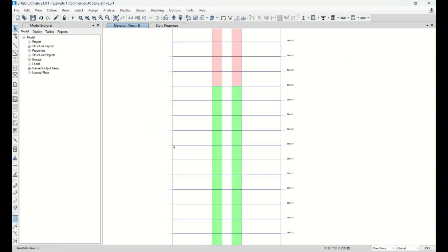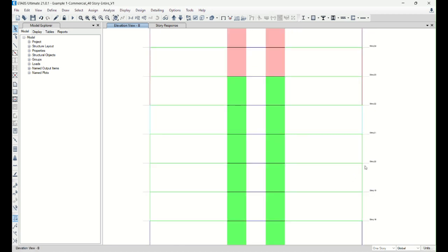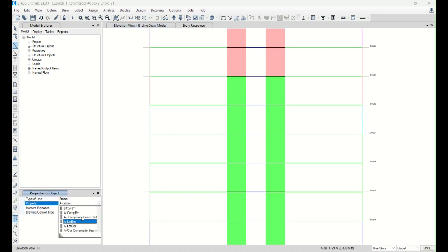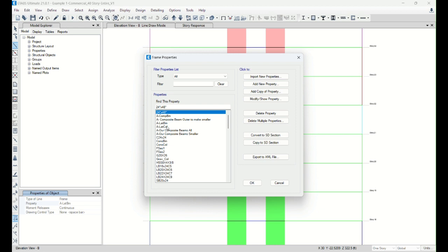So right here. Typically a high-rise building needs mechanical space, which may be at middle height. I'm going to choose the floors between 20 and 22 and draw the truss element. Similar to auto select, let me see, maybe I can create an auto select. Do I have a bracing? Okay, I'm going to go to define section, frame, lateral column.